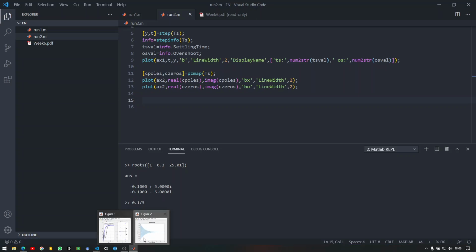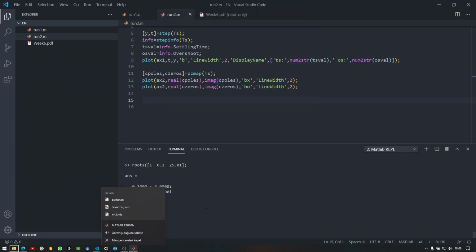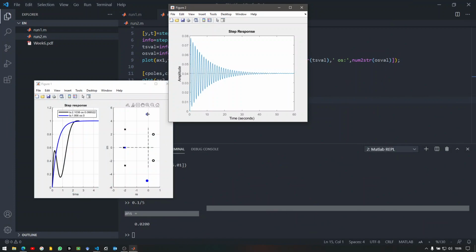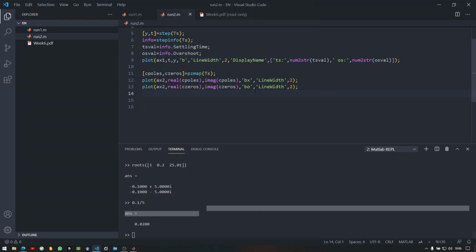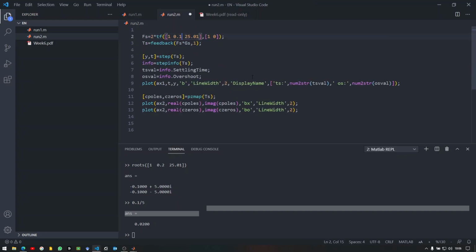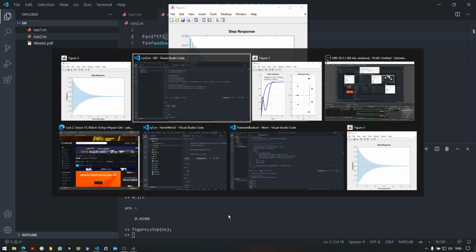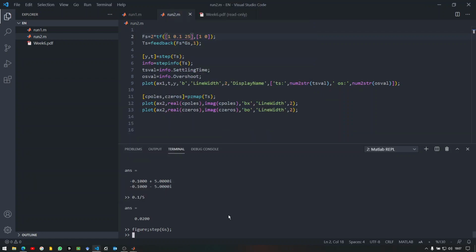Now what my filter structure in my controller does here, or this pole zero cancellation, corresponds to the band stop filter, notch filter. Now I don't have to choose them exactly at that point. I might also vary it a little bit in terms of the real value, in terms of frequency. I can also come up with an almost pole zero cancellation, and this should also work, but it would mess up a little bit of the time characteristics of my closed loop.